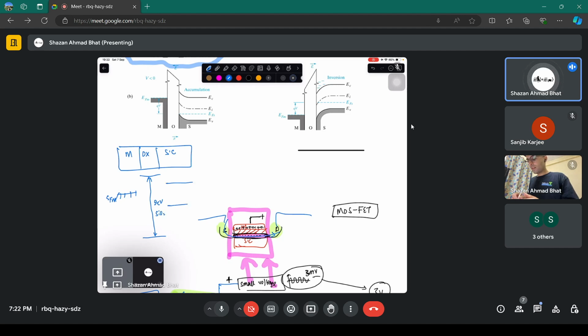And then there is the semiconductor, which is EC, EF, EV. So in the equilibrium scenario, all of those Fermi levels want to be aligned. Even an oxide has, I should say, a Fermi level, but that is in the middle of the oxide. So all of those Fermi levels get aligned. Every system has a Fermi level. It doesn't matter whether it's oxide, metal, or a semiconductor.